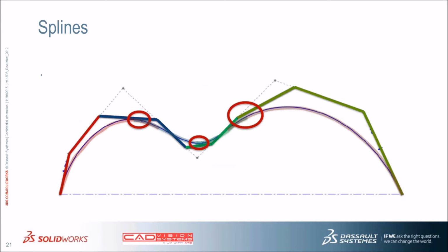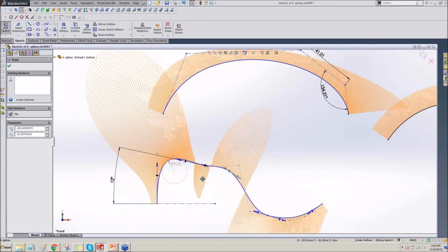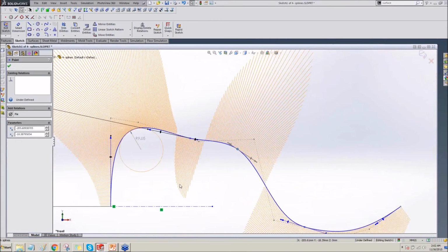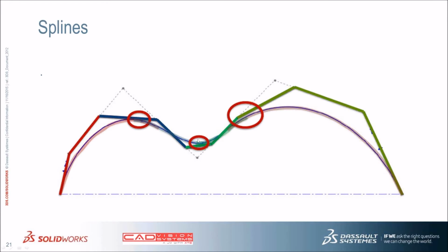So this is now a little background about splines. As it is a B-spline, as opposed to a style spline as mentioned just now, a spline can be made up of several spans. In this case, this spline here has 1, 2, 3, 4 points, so there are actually 3 spans here.